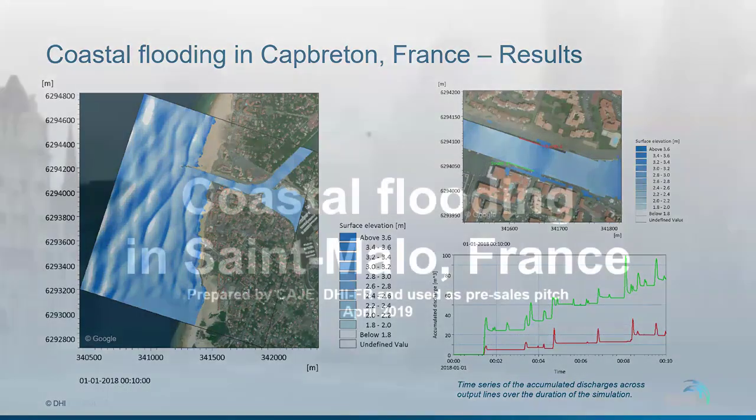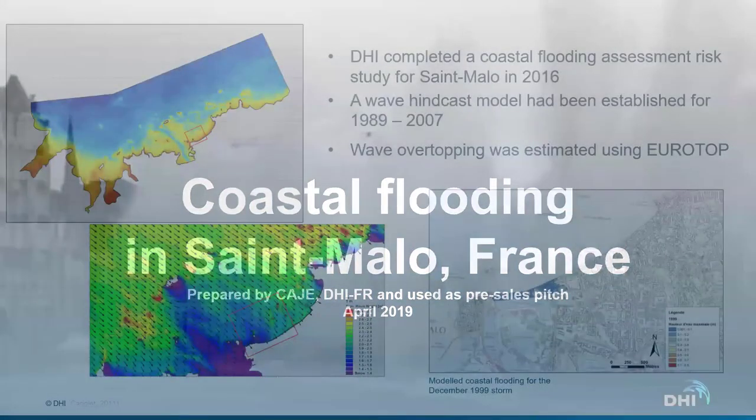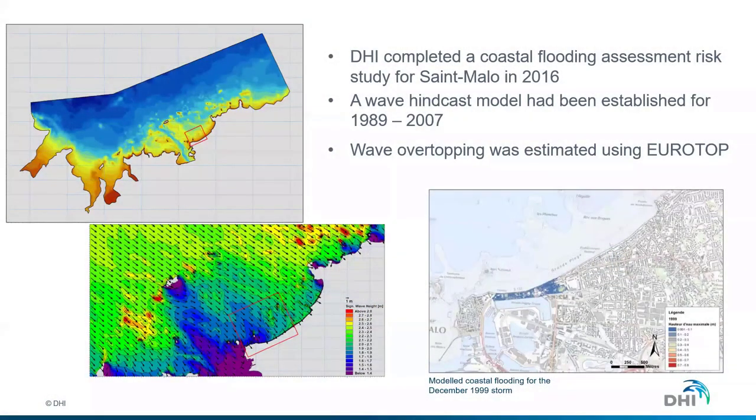Another coastal flooding study is in Saint-Malo in France, which has also been used before in April. Here we are considering Saint-Malo, where we have a coastal flooding risk assessment study. We have waves coming from the northeast, propagating through the domain and hitting the beach, where we have used the EurOtop manual to come up with some approximations for the overtopping.